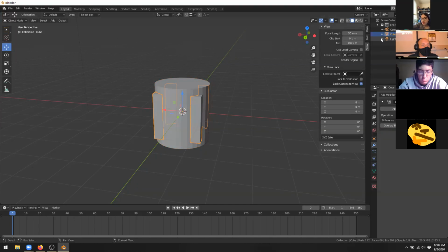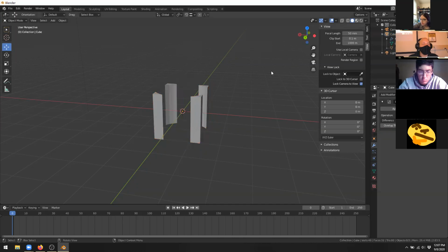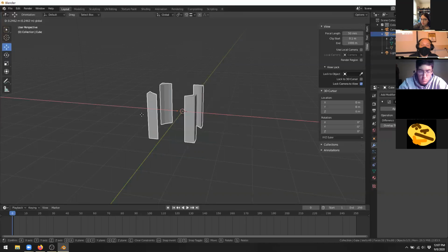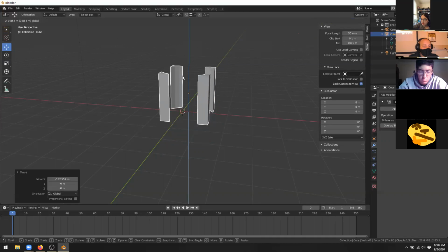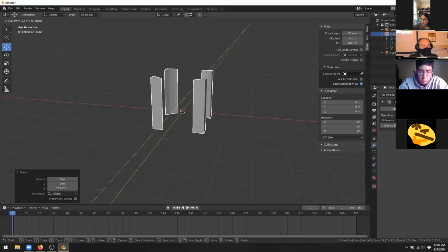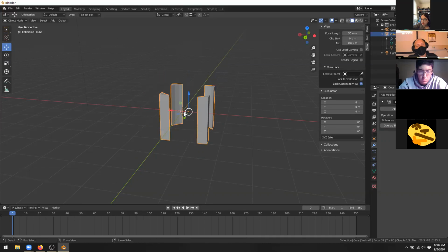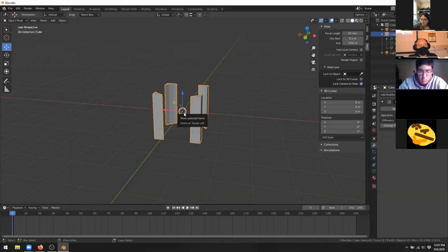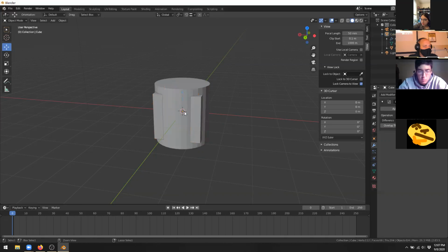Of course, from there I have to expand it to find the cylinder. But if I hide the cylinder and get back to my default state, I can move the square around and I see the cylinder is moving along with it, even though it is just a Boolean subtraction. All I did for that was set the parent object to be the cube, and the cylinder follows it. I'm going to undo a few steps just to get back to where I had it originally, where the cylinder and the cube are two separate things.